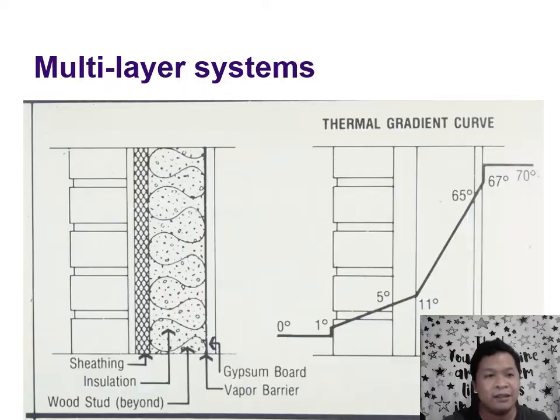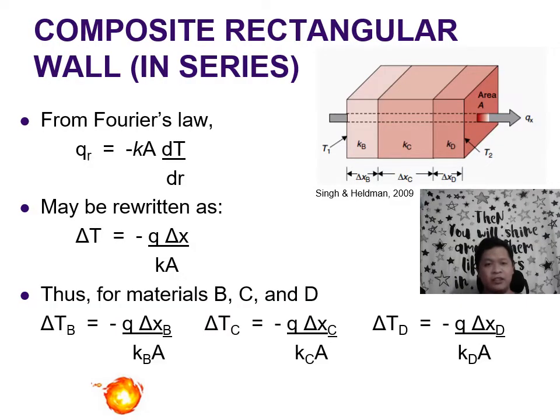capacity. So if you were to recall our thermal resistance concept and Fourier's law, so if we have a multi-layer wall, so halimbawa ito yung wall ng ref nyo, may tatlong layer dyan, each of a different material with a different thermal conductivity value. Therefore, though you would have an overall temperature gradient from point 1 to point 2, there are individual temperature gradients dun sa intersection ng kada material mo. And if you were to use the thermal resistance concept, we could look at these, no?